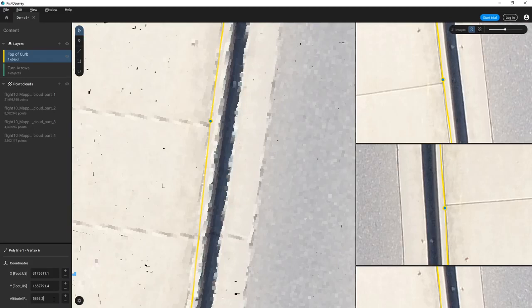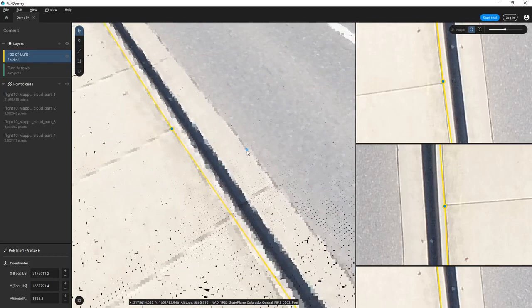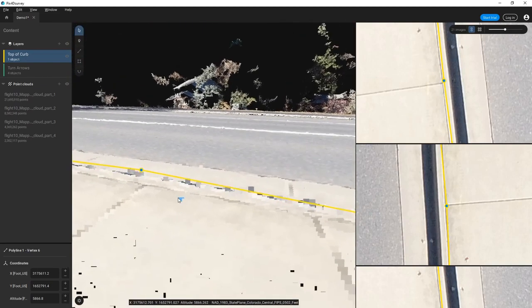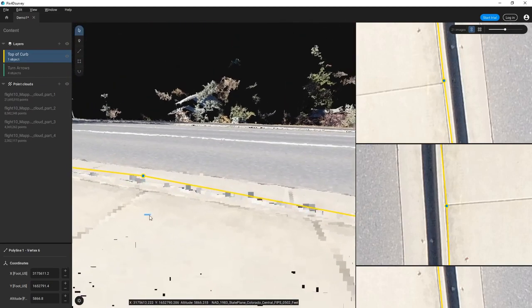So in this case, when I use the stepper, it'll move by tenths of feet. So we don't have explicit unit controls yet, so it's always going to be in the coordinate system units that you're working in. So now we can't see too dramatically because there's enough points going on there. It is no longer linked to the point cloud, but we'll be able to see that really well now that I've pivoted it up and totally away.